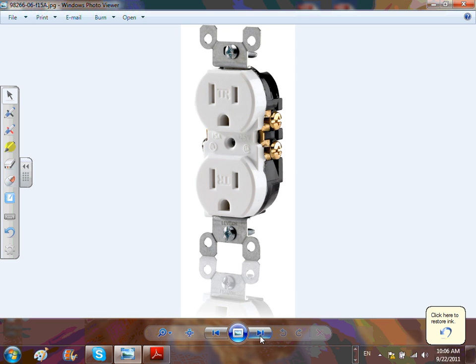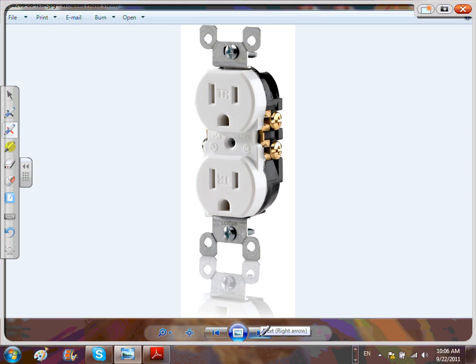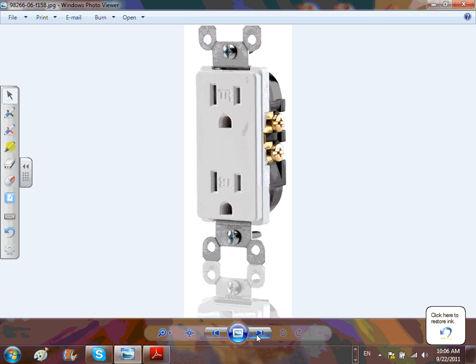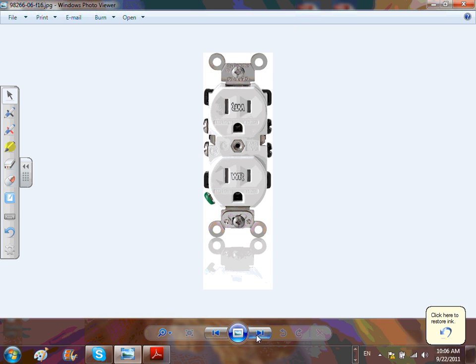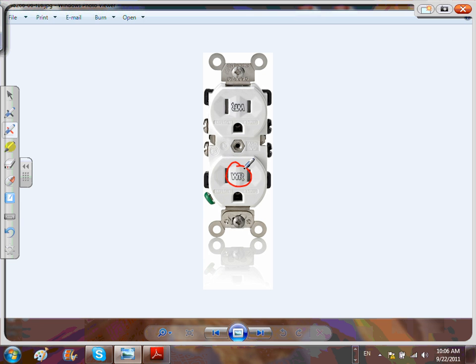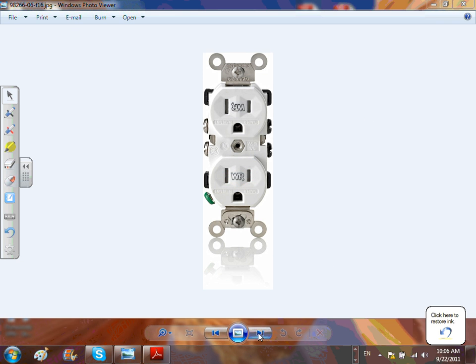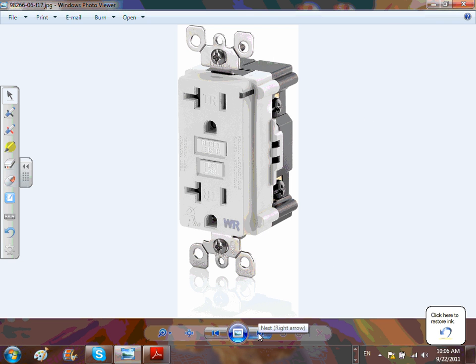Tamper resistant. Tamper resistance, you guys, I showed you the other day, TR tamper resistant receptacles. If we had a few of them, underground, tamper resistant receptacle, weatherproof and tamper resistant, weather resistant receptacle, as you can see here. Everybody knows why weather resistance in damp and wet location, because we're just tired of these pieces of equipment falling in our hands. This is required in every wet and damp location.